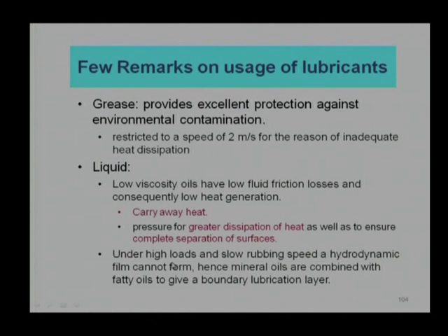However, if these low viscosity oils are not able to give good performance because of high load condition or slow rubbing speed, when the hydrodynamic action is not made, then we can add additives. In this case, we say mineral oils can be combined with boundary additives, or can be mixed with EP additives to give the desirable results to us.